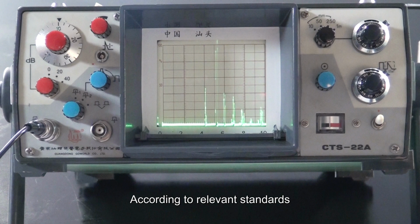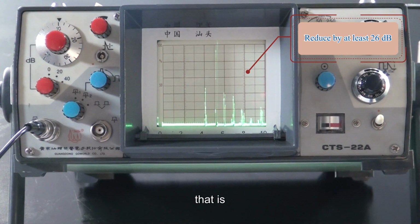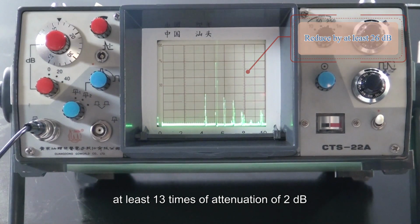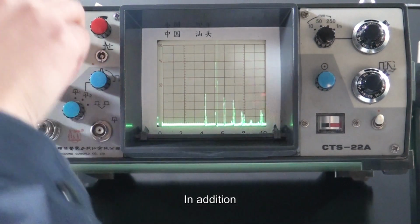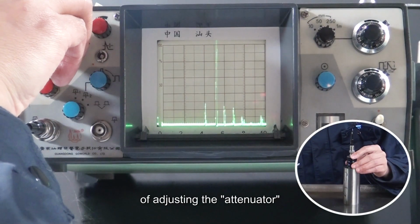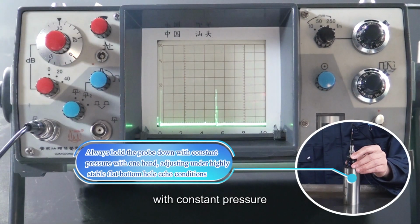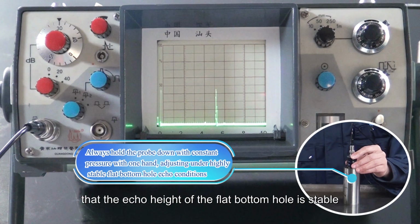According to relevant standards, this process requires attenuation of at least 26 dB, that is, at least 13 attenuation steps of 2 dB, and 13 measured wave heights are recorded. In addition, it should be noted that during the process of adjusting the attenuator, one hand should always hold the probe with constant pressure to make the adjustment under the condition that the echo height of the flat bottom hole is stable.